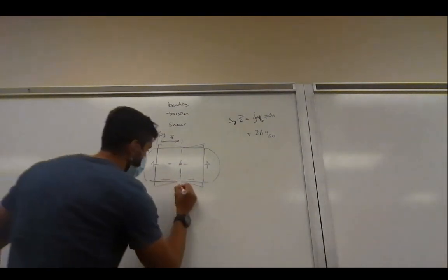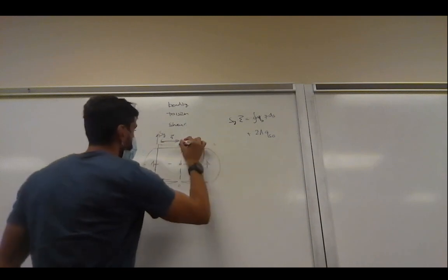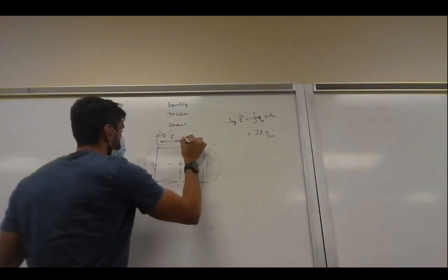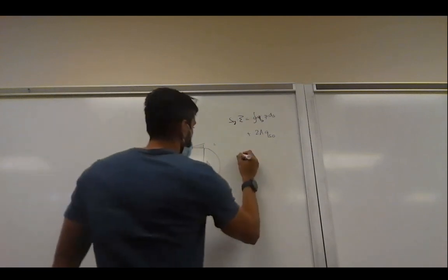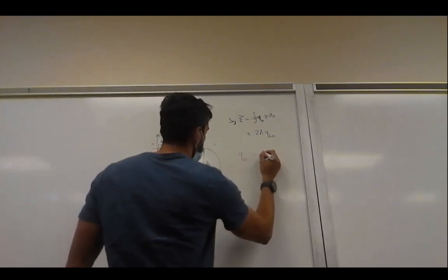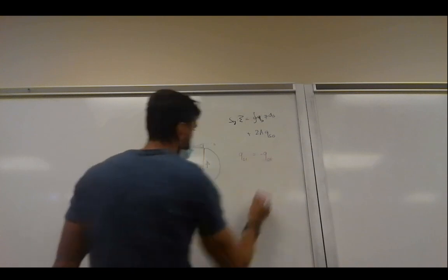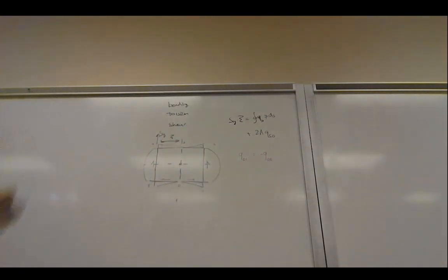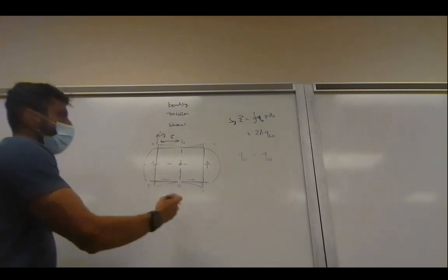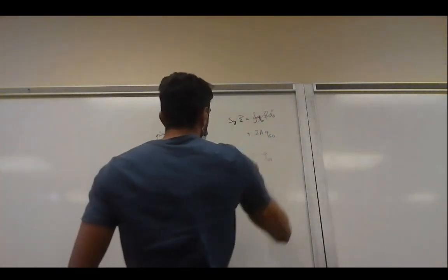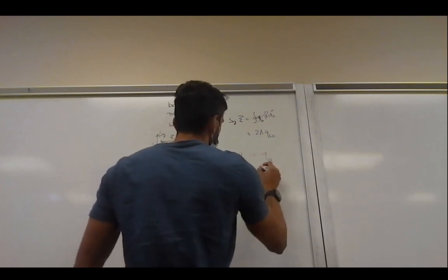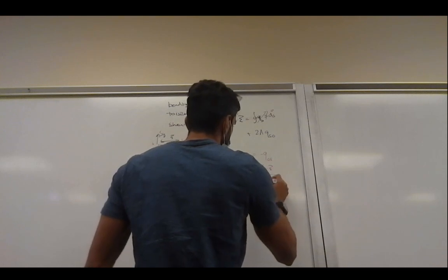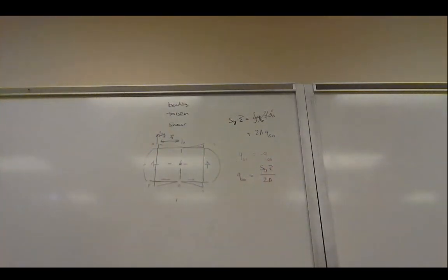So if this is 0, 1, and 2, let's call this 3, 4, 5. q01 is basically the negative of q05 because they're symmetric but go the opposite way. So the moments cancel each other out, so this becomes basically 0, and the correction shear flow qs0 becomes Sy times ξ over 2A, right? This is what I just said.